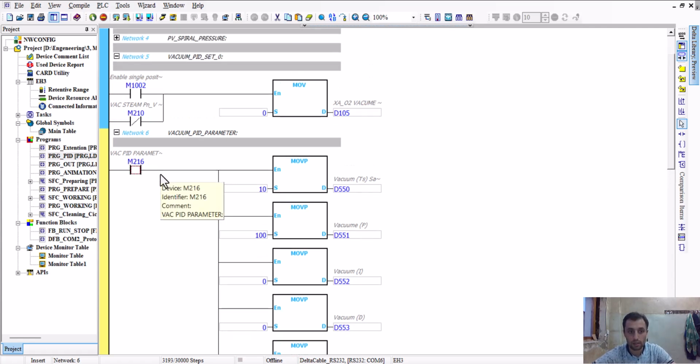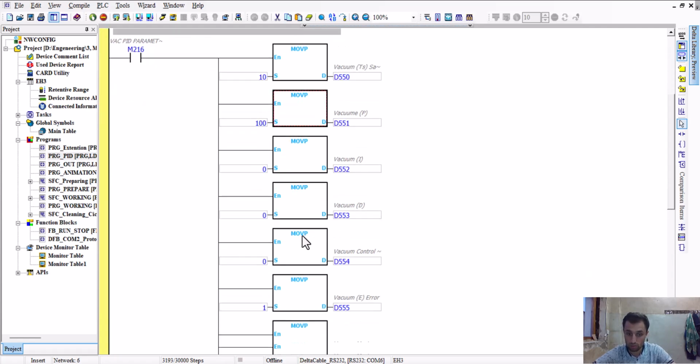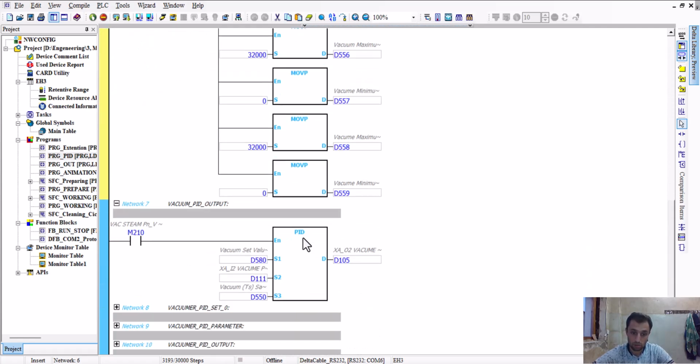And it is better that when the PLC is running, or when we are not using PID control, you make your output zero. Otherwise, for example if you are using an actuator, it keeps the previous value for the opening, so that remains, and when you start your PLC it continues that way.